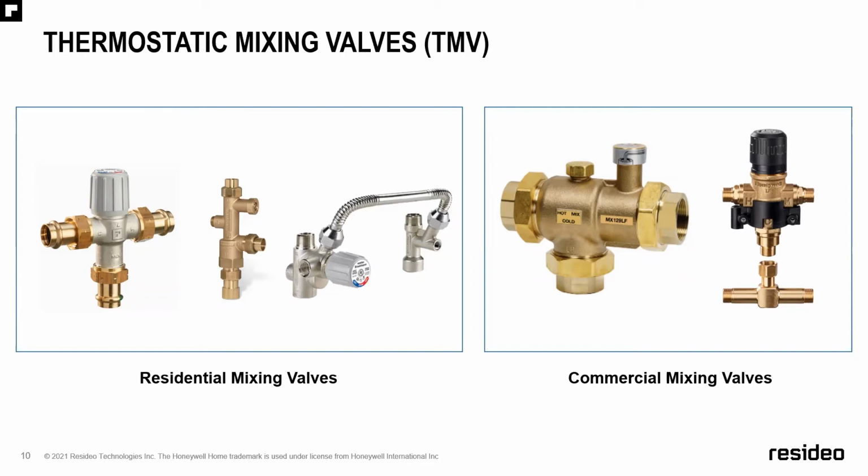And then even better, we have an under the sink mixing valve, where the AMX series is great, but it could be costly in certain spaces. The MX is a very low cost under sink mixing valve, which is point of use. They both have 3/8 compression on either side, so it hooks right up to your water lines. You can use it in a 3-port application or a 4-port application, and we actually supply that 4-port T without ordering it separately. So it's a really nice feature, really inexpensive, and has a lot of value to better your outcome.